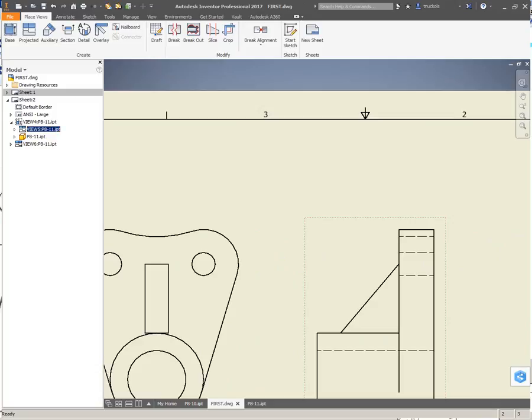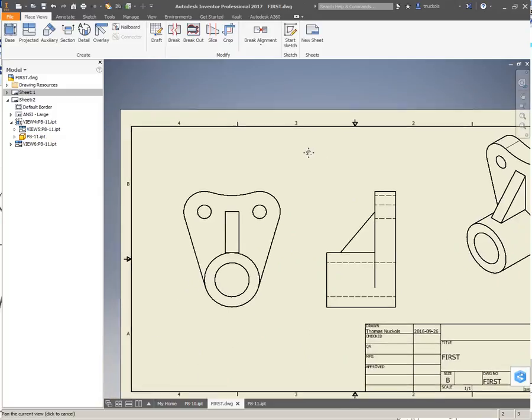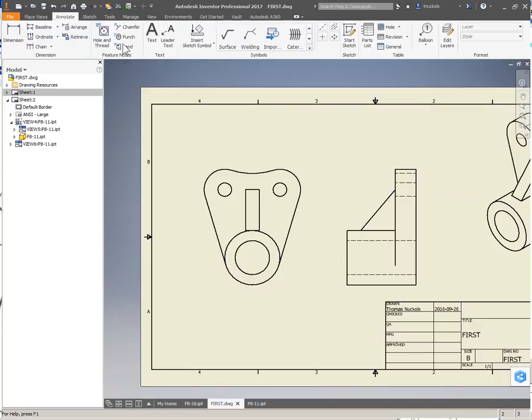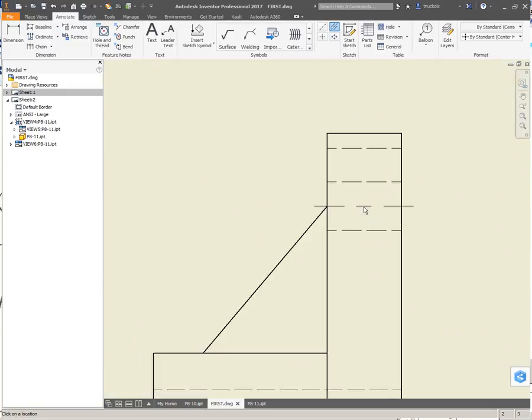Let's go ahead and start annotating this thing with center marks first. Click on your largest circle. For this you need to click on the largest arc and then the circle. Let's do centerline bisector here. And there. So now we've got the center line going through that hole.